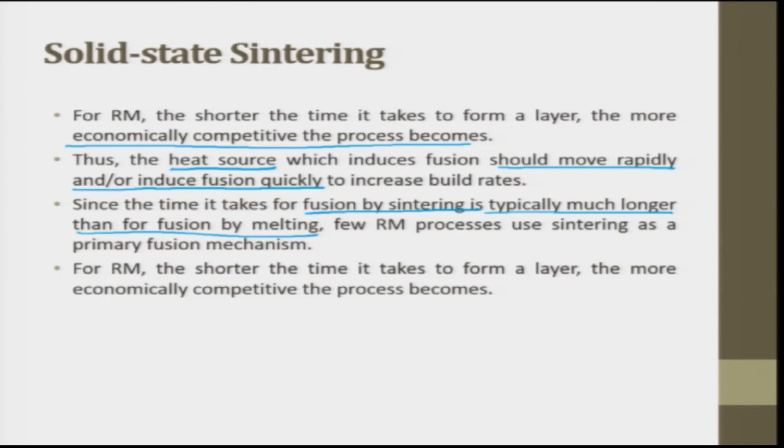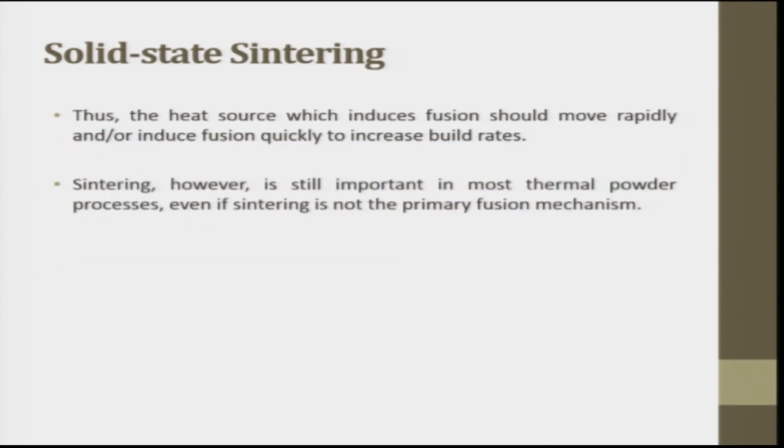For RM, the shorter the time it takes to form a layer, the more economically competitive the process becomes. Thus, the heat source which induces fusion should move rapidly, inducing fusion quickly to increase the build rate. Sintering, however, is still important in most thermal powder processing, even if sintering is not the primary fusion mechanism.